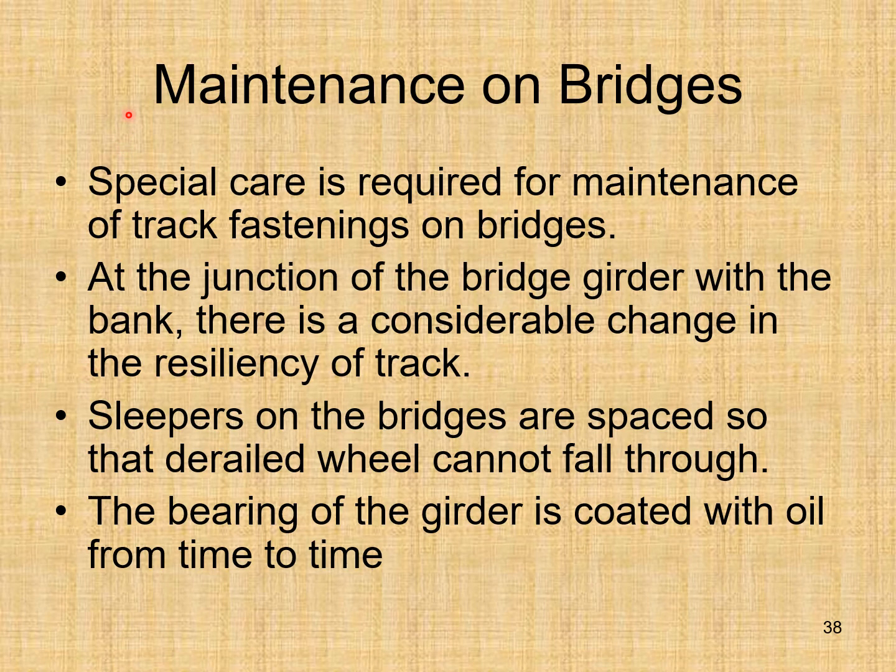Maintenance on bridges. Special care is required for maintenance of track fastening on bridges. At the junction of bridge girder with the bank, there is a considerable change in the resiliency of track. Sleepers on the bridges are spaced so that a derailed wheel cannot fall through. The bearing of girder is coated with oil from time to time.